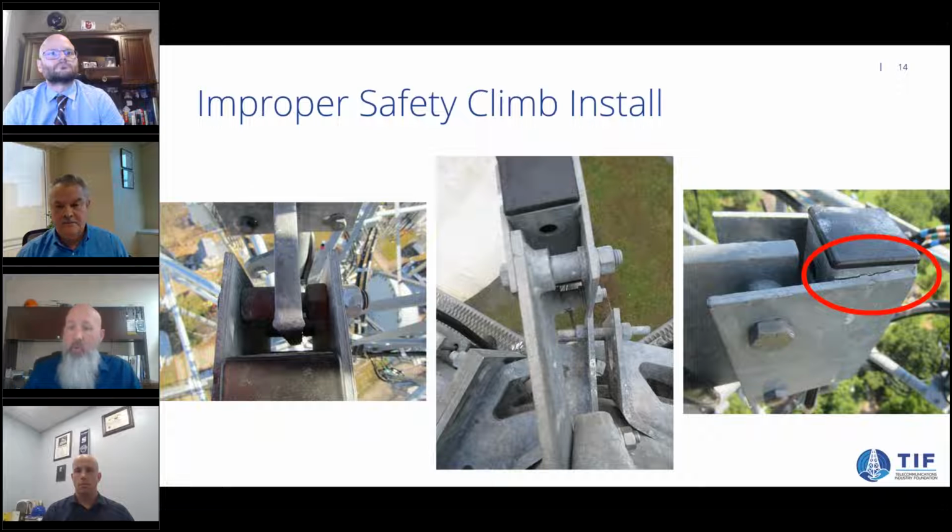Then in the third photo on the right, we can tell where we probably have improperly sized spacers and a little bit of force was used, and we actually cracked the weld on that top head assembly.